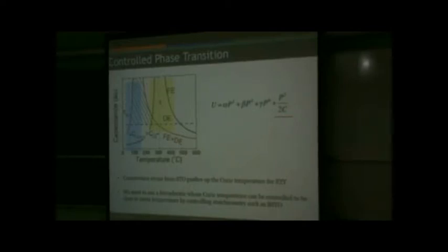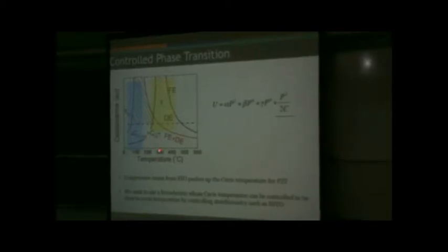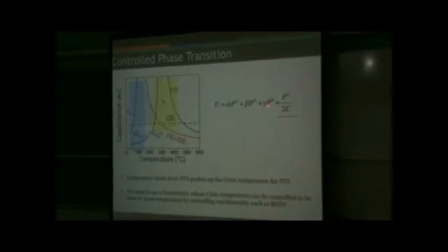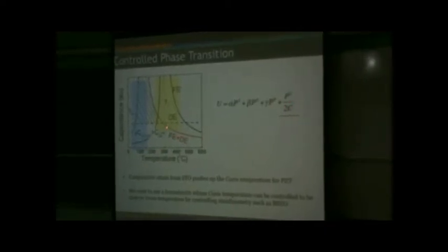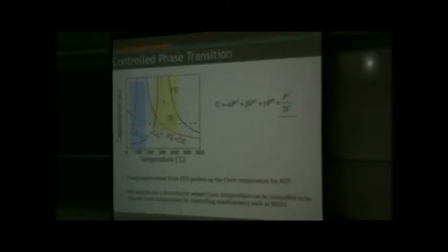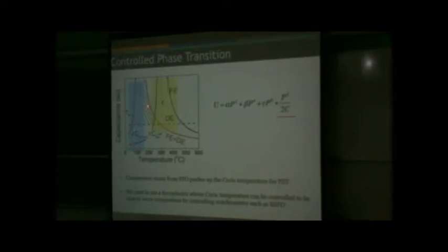What that means is, let's say my isolated ferroelectric had a Curie temperature around, let's say, 300 degrees centigrade. By putting the dielectric capacitance in series, I am actually pushing the effective Curie temperature towards a lower temperature. Therefore, if I can be in this hatch region, my permittivity will be extremely high, and you can now start to bring in all this positive feedback mechanism. That is actually part of the Landau-Ginzburg field theory anyway.